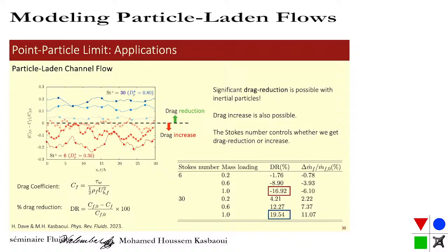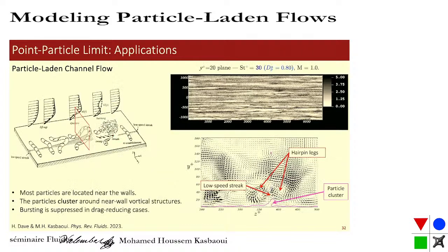and a drag reduction which is significant, about 20%, with the larger particles. The reason why we care about this is because this project was funded by the Petroleum Research Fund, and they care about transport in pipelines, so anything that can reduce drag in a pipeline is something of interest to them. And using spherical particles is interesting because these particles will not break up compared to other polymers that people have been using. So they're longer lasting.